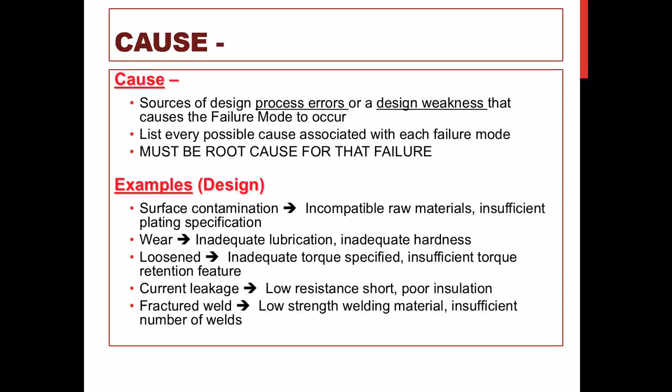Or it could be that in order to get a perceived failure on the product, I have to have two failure modes occur on a product before the customer will notice that they have a problem. Either way, each failure mode that is caused here is a line item in the design FMEA, and if you have more than one effect, then that failure mode is going to get listed twice for each effect with each root cause.